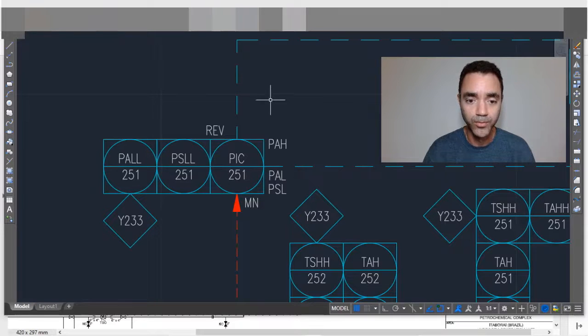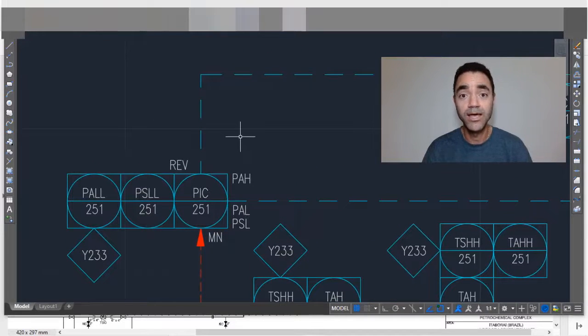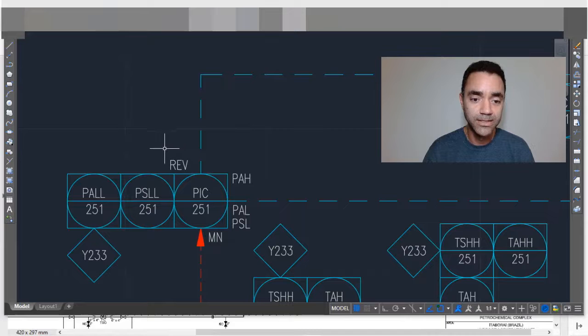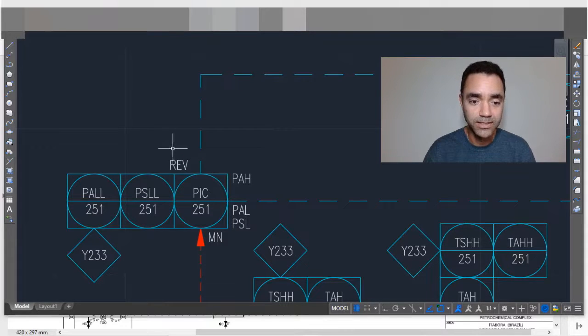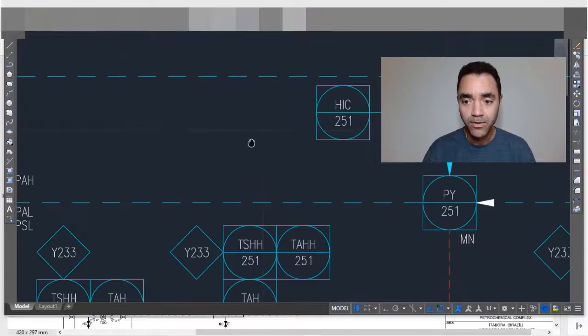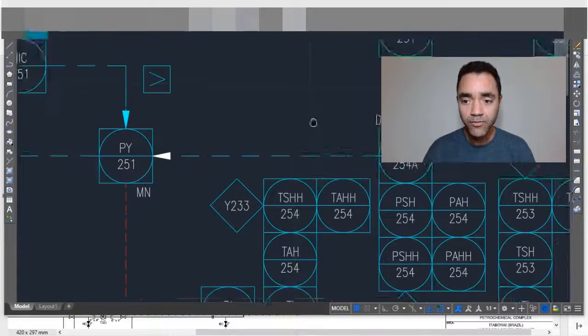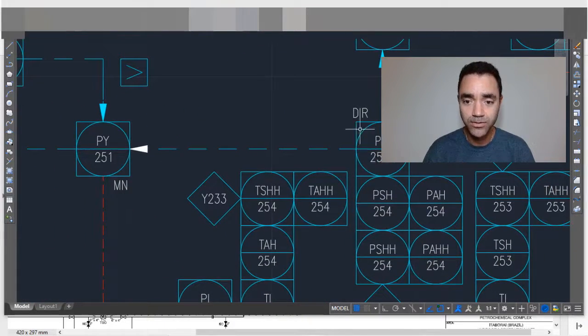You can see that kind of recommendation in the ISA, where you identify which kind of interlock is associated with this control loop. And information that we have not seen in the previous piping and instrumentation diagram and is not shown too often is the action of the controller: if the controller is direct control or reverse control. In this case, for the suction pressure controller, we have a reverse control. On the other hand, for the discharge of the compressor, we have a direct action.